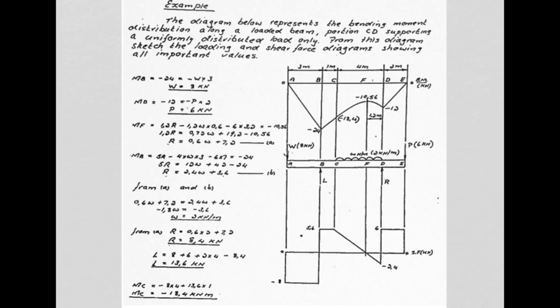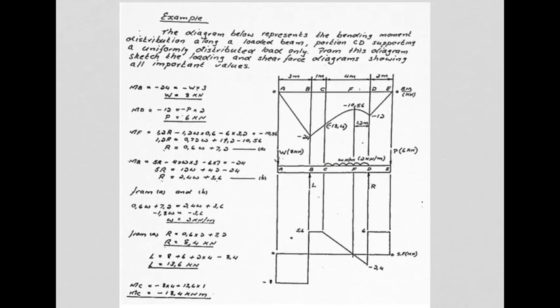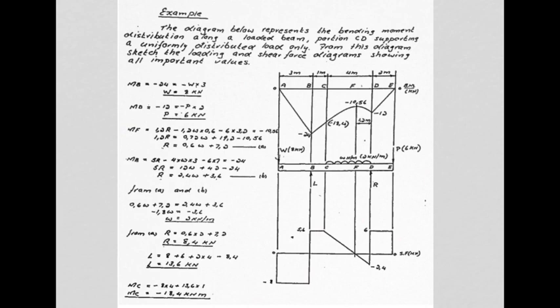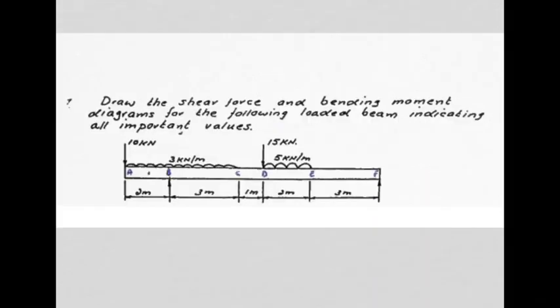And once you have the various loads, you can then draw the shear force, knowing that between C and D it was having a UDL, so therefore it is sloping. You can draw in the UDL and even figure out its magnitude. So try that one. And once you're done, have a look at that solution. And another one to practice on.